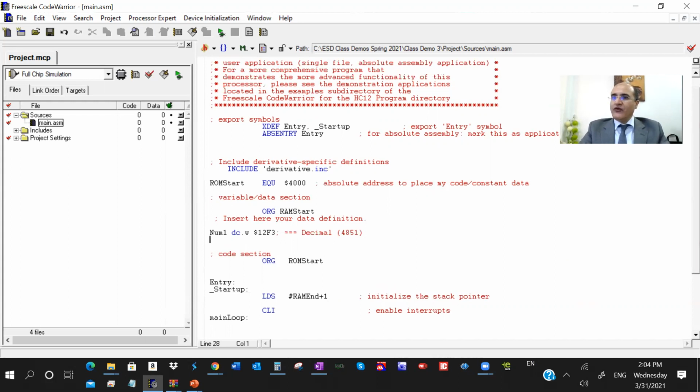Then we're going to book 4 bytes for the BCD number, because they're 4 digits. Each one of these should be stored in one location. Okay, so we need 4 locations. We book them. So we can say number BCD, reserve memory bytes, 4 locations to store the 4 BCD digits later.